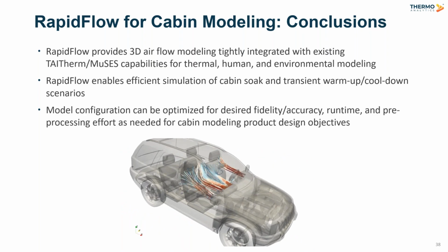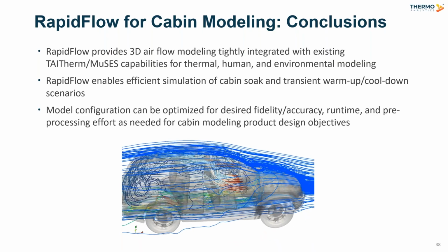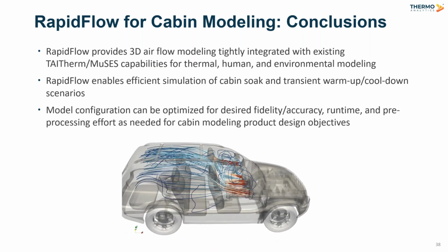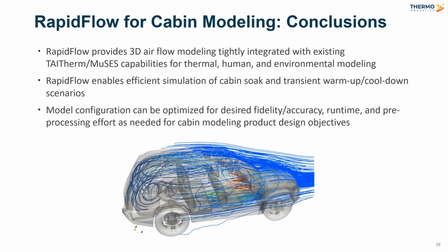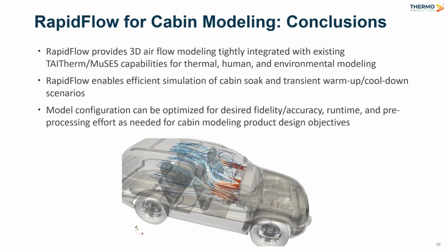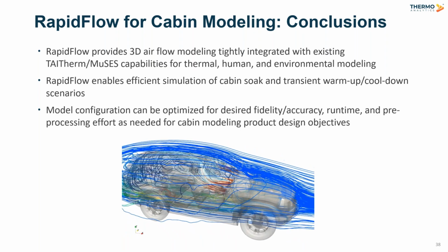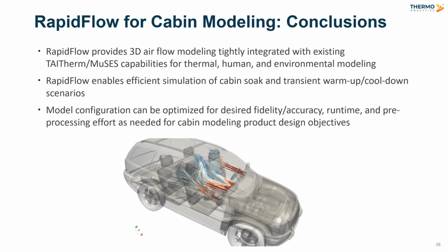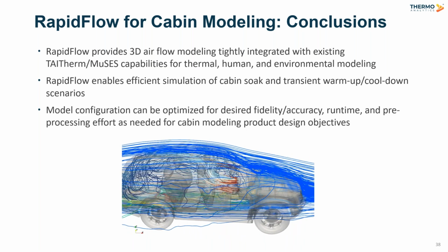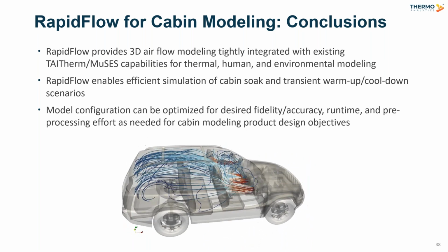That, of course, can be one area where the differences in fidelity or accuracy are apparent, if you're looking at something that really does require a detailed boundary layering method. But part of what we were trying to show in the cabin example here is that if you step back and look at the results of those flow predictions in terms of how they affect thermal predictions, comfort predictions, things of that nature, there may not always be a strong dependence on those high fidelity boundary layer modeling techniques.